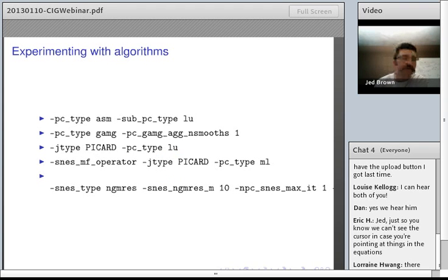So there's some other directions that we can experiment. We can start using a preconditioner. So the default preconditioner, if we've assembled, so suppose that we've done more work now so that we can assemble the Jacobian, we can look at, say, an additive Schwarz method, which will use some overlap.